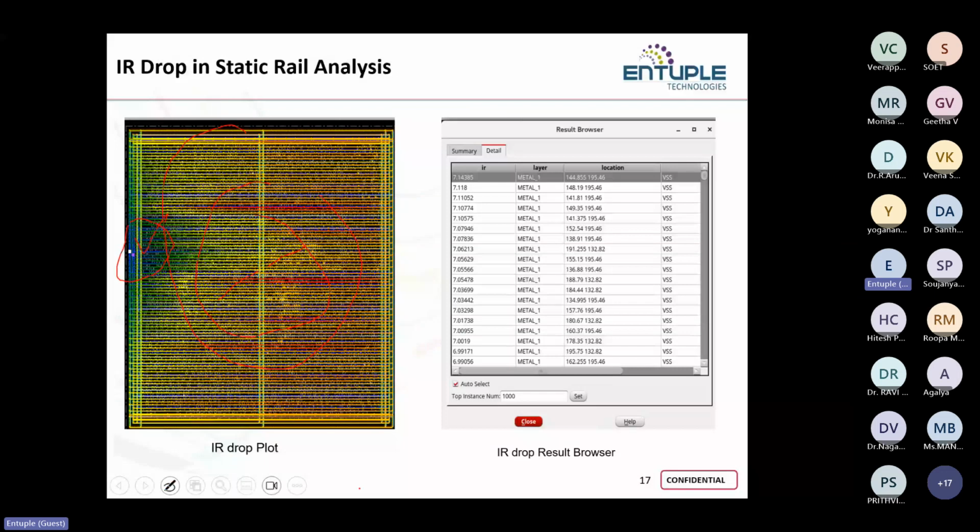One thing you can observe here. Here we disable the standard cells. We are only looking at the stripes, rings, and the power network. These are the mesh power network. So for power-related IR drop, we are mainly analyzing these metal layers, the power network metal layers, the power distribution network